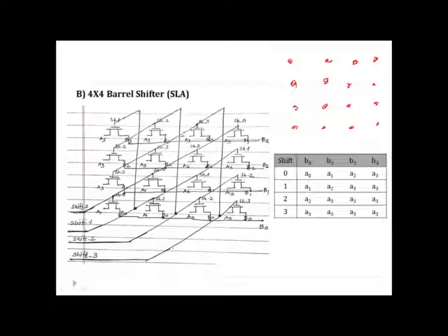Now I will start from diagonal elements. So first I will go with shift 0. Remember, the first diagonal is shift 0. For shift 0, like I told you, when you draw barrel shifter operation, you have to focus on input and outputs. Now I have already drawn the NMOSes. For the first, shift 0, A0 input and B0 output. I have to just mark A0 at the input and B0 at the output. That's it. Remember that I have already drawn NMOS. Then next is A1 B1.